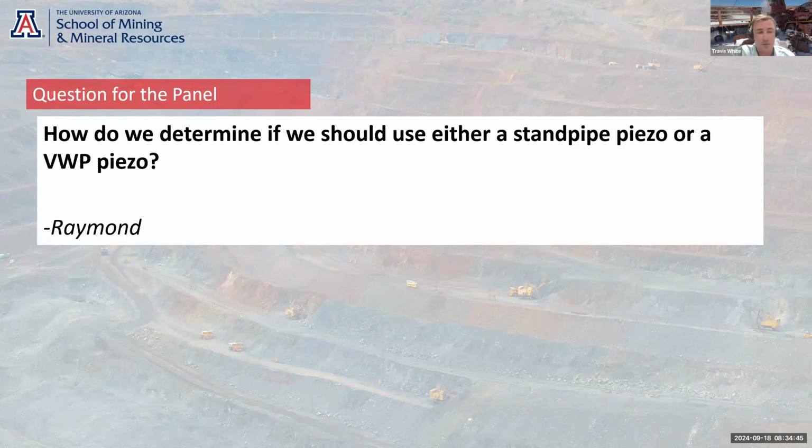Just a last comment, Jill, on the deep multi-level installations we did at one of the sites that was high K, high flow, highly fractured. What was really useful was the regional recharge; we picked up a lag. The underlying dolomites were the regional aquifer that was feeding the mine, and there was a three-month delay in the response to rainfall. So we picked it up in the dolomites before we picked it up in the other units. That was a nice early warning for the mine that this recharge was happening. Ultimately they all leveled out, but there was a bit of a lag there.